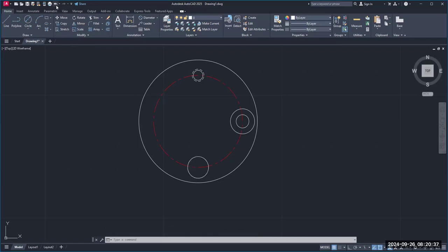You're fine. I'm going to undo mine. I'm going to go to circle, center diameter, type in quad. By the way, there's an easier way of doing this. I'm showing you the hard way first. Enter and click, drag out my diameter is 0.44. Enter. Now I want to draw another circle, a concentric circle that has a diameter of 0.27.